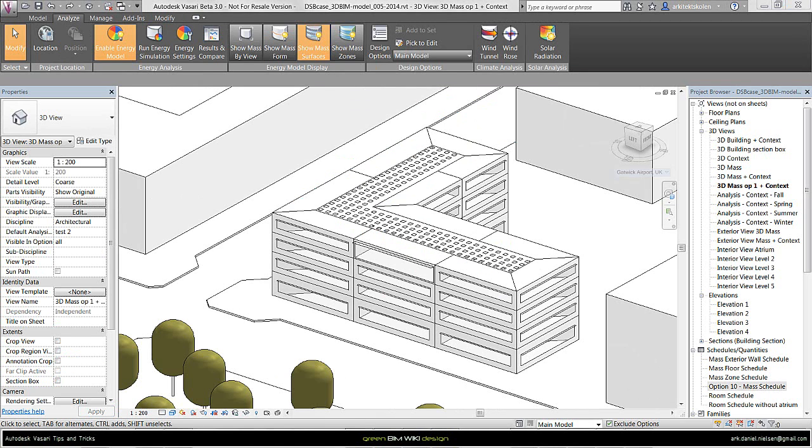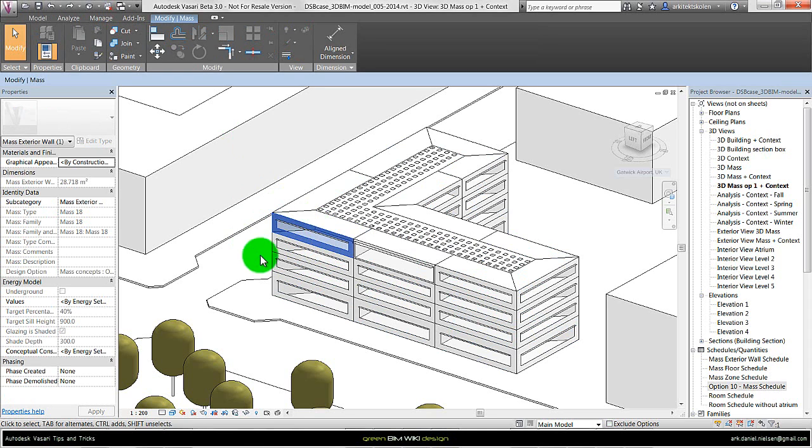If I want to customize the facade openings even more, then there is another method where I draw the openings manually, and the first thing I need to do is remove the glazing that is created automatically by the energy settings. Selecting those surfaces I want to customize manually, I remove the values by editing the energy settings to "by surface" and changing the percentages to 0. That means there is no glazing added to this surface.